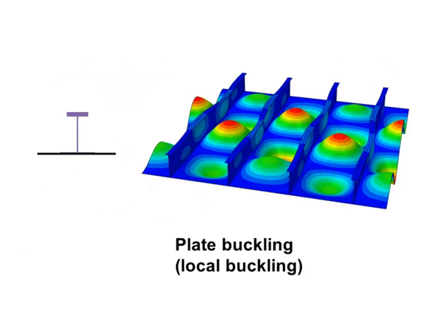All local failure buckling modes are also analyzed, such as plate buckling and crippling. Crippling occurs after the plate goes into local instability. Stresses concentrate into the remaining stable cross-section of the stiffener shape until the entire panel crushes.